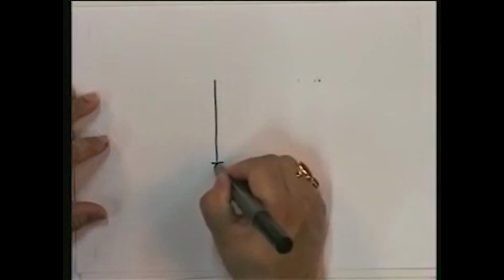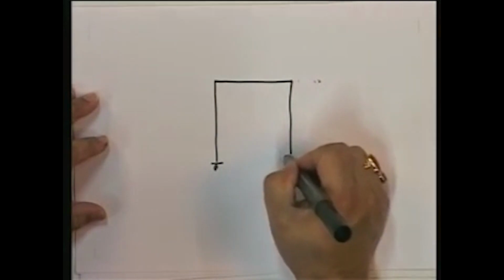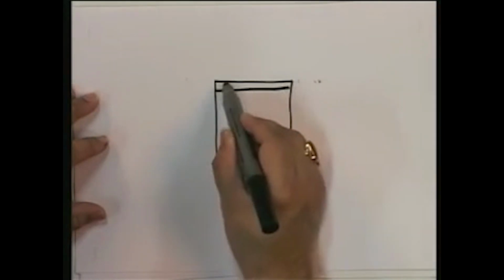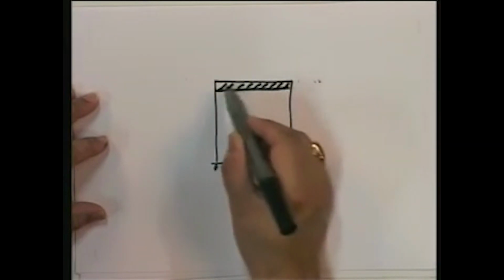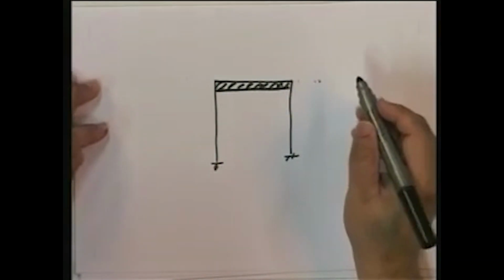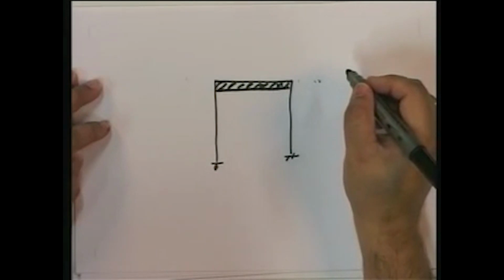Okay. So this is relatively simple. I hope that at the end of this treatise, you should be able to find out the kinematic indeterminacy and static indeterminacy of frames. I am now going to show one more constraint, because you might have a constraint like this. Think about it. And this beam is totally rigid. In other words, this beam cannot deform axially or flexurally. What happens in such a situation?